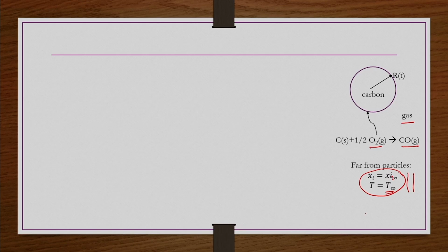In fact, because of that constraint of not having any information about the concentration or temperature at the surface, we are forced to go for some kind of a pseudo steady or quasi steady analysis, right. So, now I will draw a dotted line here, just outside of this circle, and I am designating it as R plus, which is nothing but the very first layer towards the gas stream. And inside this carbon particle I am drawing another circle, which I am calling R minus, which is the very first layer towards the particle side.